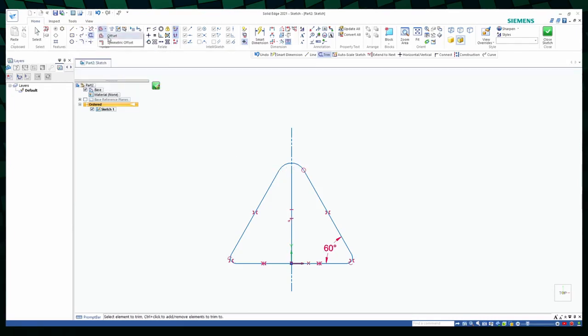The last interesting feature we're going to see today is the offset command. It basically does what the name suggests. By selecting a certain distance and the sketch, you can offset it by the distance you've typed in. Here's one interesting bit. If you select single up here in the menu, it will just select one of the edges, either a round one or a straight one. And if you select chain, you can select the closed profile of the sketch. You can do this as many times as you want in one go, both to the inside or to the outside, and when you're done, press escape.